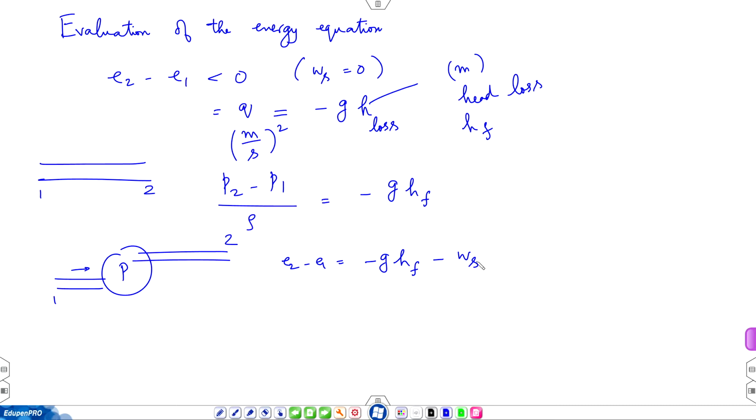So, now we have an equation. Now, a pump is a small device, so no change in elevation, no change in velocity. Why? Because let us say the tubes are of equal diameter, it is a steady flow process, this flow going through the pump, no change in velocity, no change in elevation, because the pump is a small gadget. So, it is only a change in pressure.